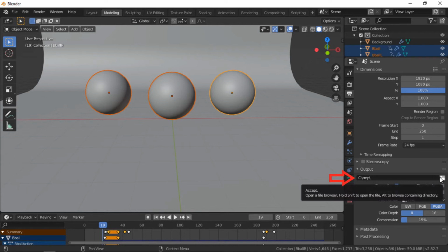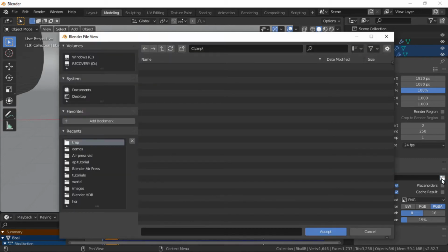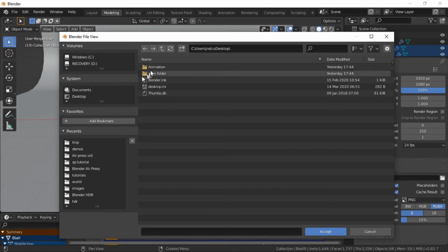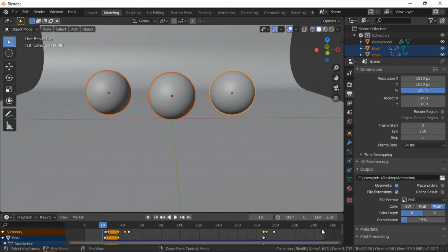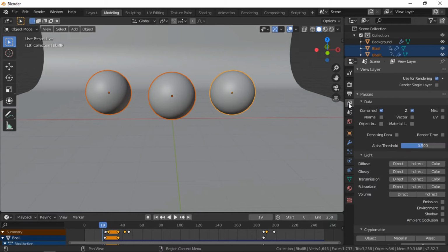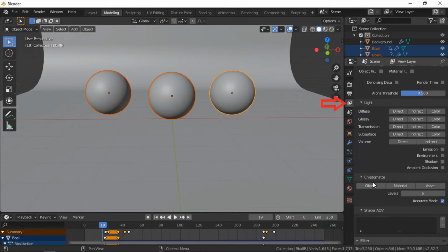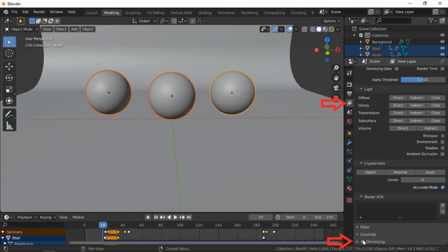The output location is where the render is saved. The default location can be adjusted to somewhere more convenient. We will now enable denoising. Denoising assists with removing fireflies and noise in the image. Denoising is enabled from within the Layers Properties menu.